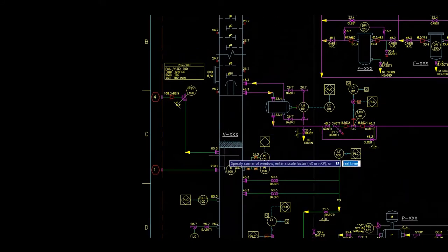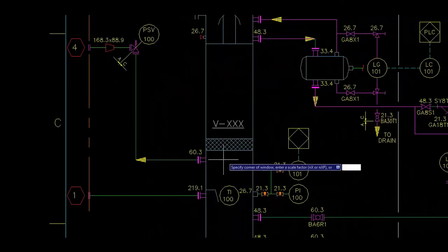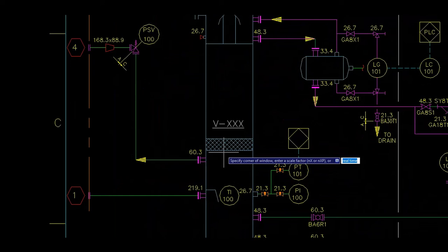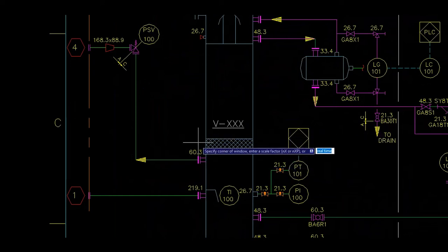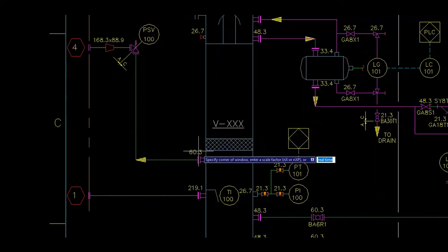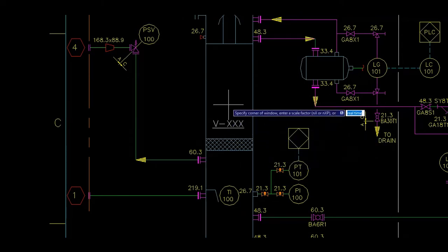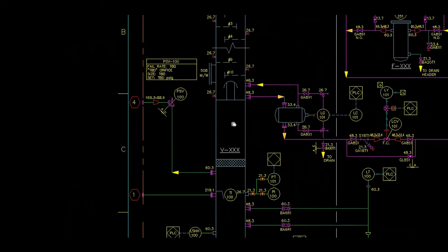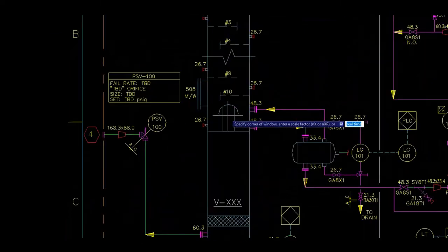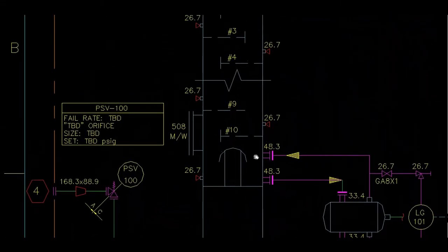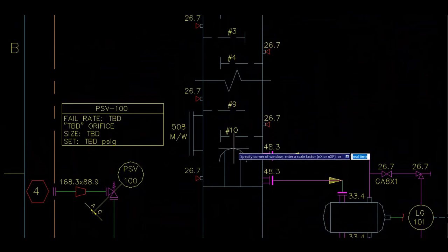Let's follow the gas path. The inlet gas that is at equilibrium, as described before, at the temperature and pressure, will pass through the coalescer just in case there should be any free water carryover with gas. The gas coming out from the coalescer is now more or less free of free water.